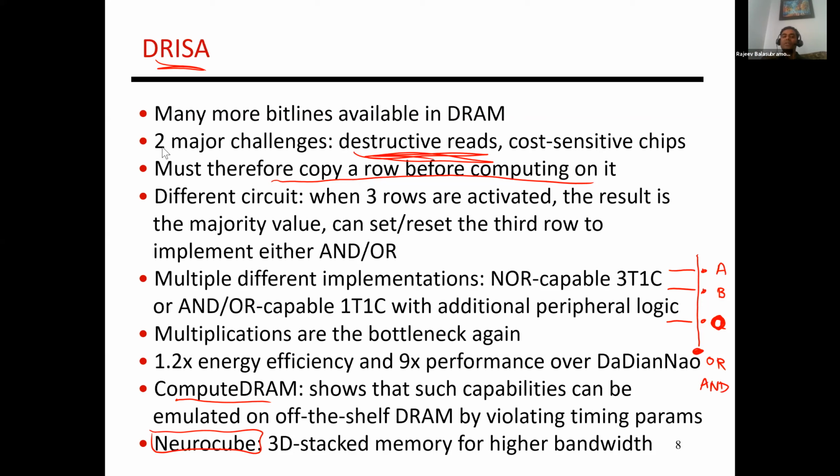Okay, so let me again just pause for questions. Somebody has asked about the copy process in DRAM, and yes, that is a significant overhead. You can copy in several banks in parallel, so the latency penalty may not be as high, but it does cost energy, and as you note, it does eat into the capacity as well. But many of these models are a few tens to hundreds of megabytes in size. Even the feature maps that you produce along the way are hundreds of megabytes. And so that's well within the capacity of most DRAM systems. So it should not be a problem.